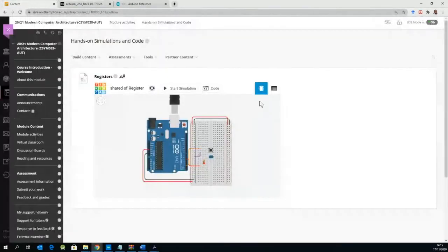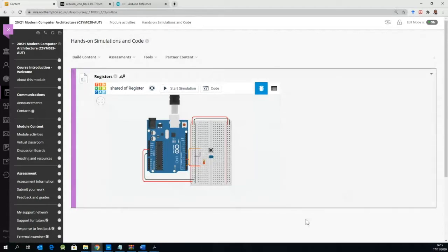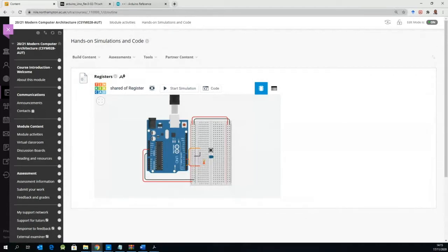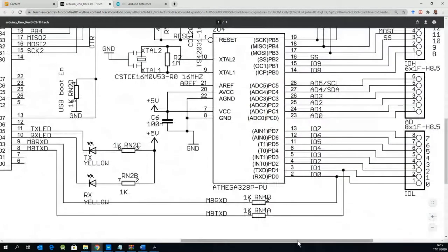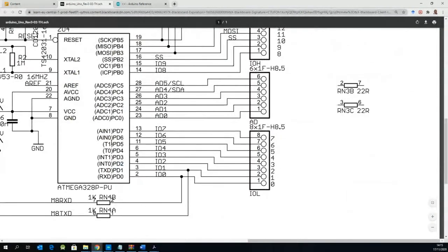Okay, so that being said, we need to come back to the port somehow. Now, that is where it gets interesting. I can go back to the whiteboard to show you some stuff. We are interested in 2 pins, pin 2 and pin 5. Pin 2 is connected to PD2. Pin 5 is connected to PD5. Now, PD2 is the switch, and PD5 is the LED. That's what we understand so far.